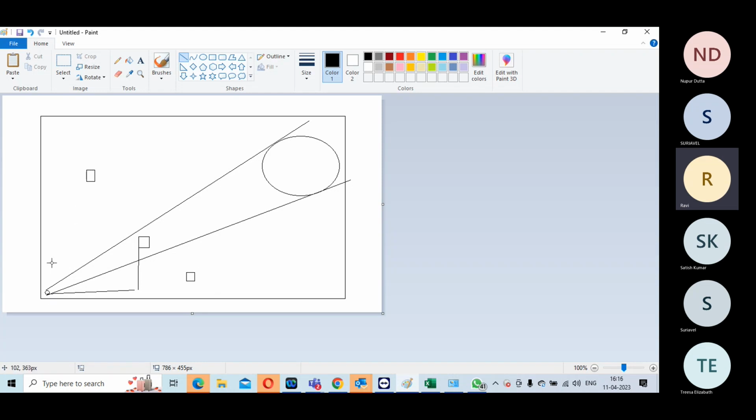this one, then what will happen is you are trying to build a long net without actually proper control. So place these particular guys somewhere in between, so that this net will spread properly, because this one will have 2-3 nets coming out of it. This clock buffer, this one, you have to really construct. I can show you with some things. So do a good job of your clock tree placement. I can explain more in detail next session.